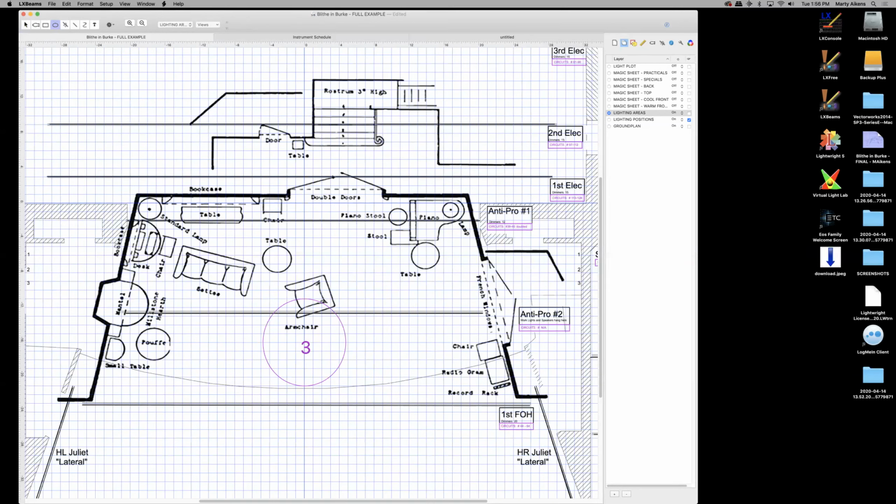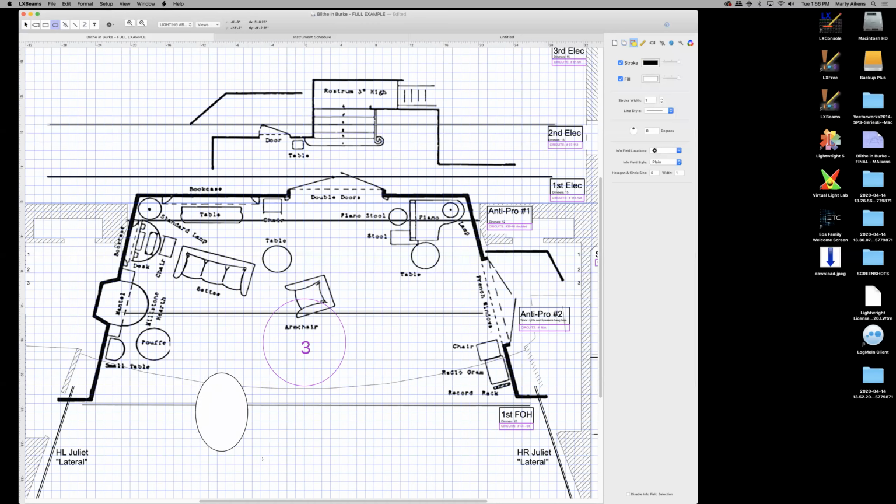I'm also going to come over here and click the drawing options tab because that's going to show me the colors that it's going to draw in. Right now, it's set to draw the outside of the circle as black and then to create a white fill. So if I was to draw that, it would look a little something like this. And I can stretch that around until it's the right shape. And when I let it go, I end up with a circle with a black line and a white fill. Well, I don't want that. I'm going to delete that.